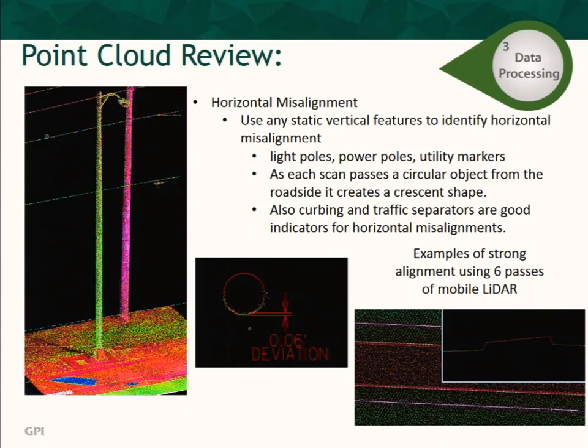And then of course same thing with vertically. You have all of these curves that are on top of each other, basically from the point cloud, and if they're aligning well, that means we have a good horizontal base. So you always take one scan as your base, and it's already been proven horizontally, vertically, and then you tie the rest of these scans to it.